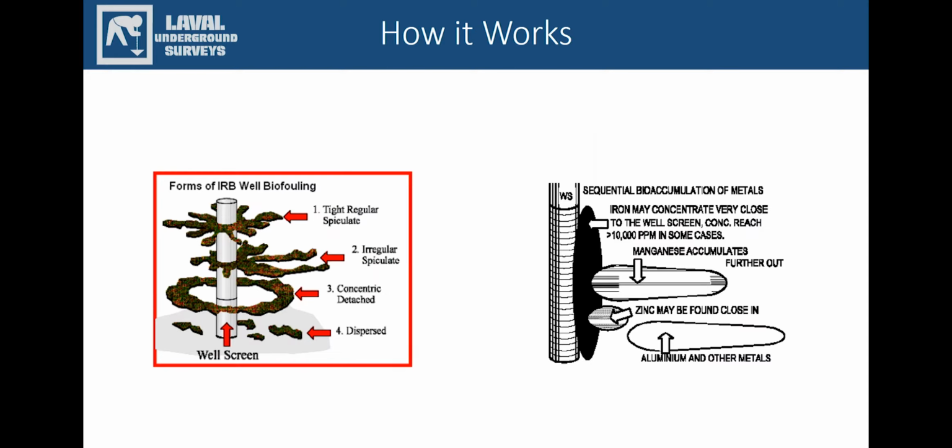Because iron bacteria is found naturally in groundwater, you'll find it further out in the casing and screens than you might anticipate. If you have iron bacteria in the well, it's likely that it will be found in the fractures outside of the screen because it also encounters oxygen there. The biofouling forms communities that do not get washed away with the ingress water flow. Iron tends to concentrate closer to the screen, but manganese fouling can accumulate much further out.